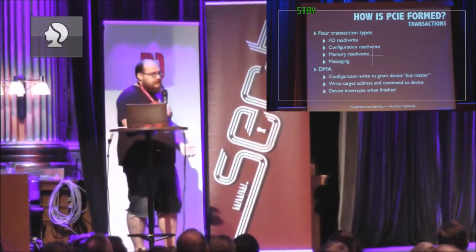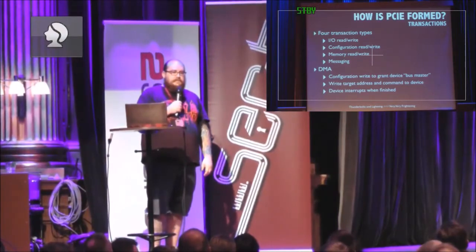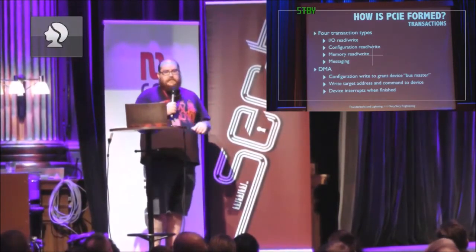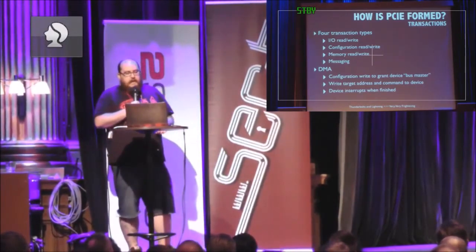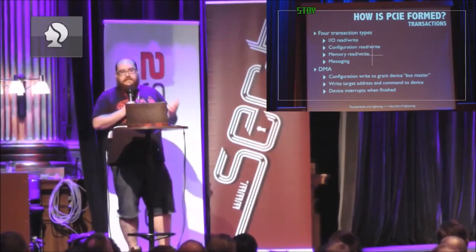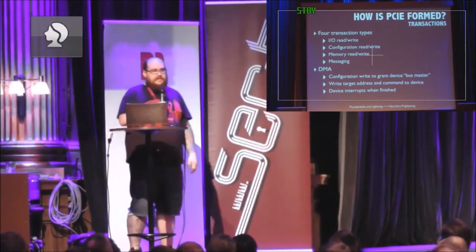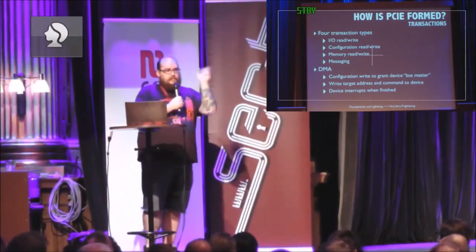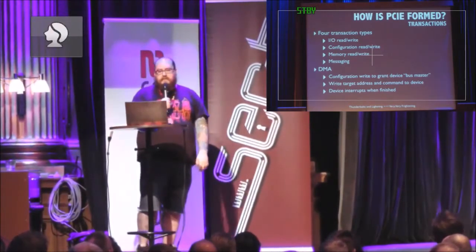And then we've got messaging, which is for signaling interrupts. PCI Express supports level sensitive interrupts on pins on the CPU or on the PCH, but most interrupt driving now is done by message signal interrupts. So you build a little MSI packet and you write it to a specific address with a DMA write command, and then that becomes an interrupt in the APIC.